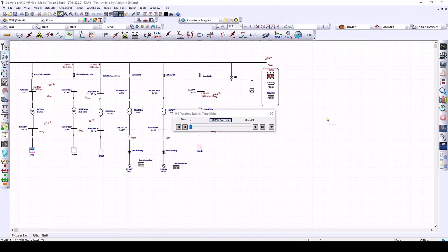It's important to mention that the ETAP Microgrid Controller solution is a model-driven technology. Basically, the user can first develop and modify all the function blocks, and add and change any settings in the controller logic. Then the performance of the functional logic and blocks and all the settings can be evaluated in the ETAP software. Once the user is satisfied with the result, the developed functions and settings can be transferred to the ETAP controller hardware to function in the actual system.